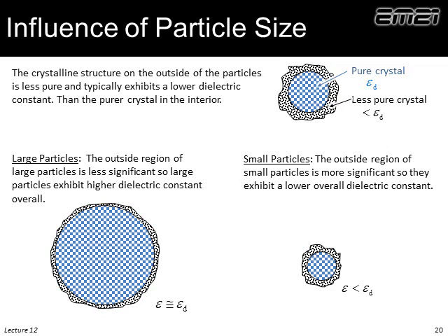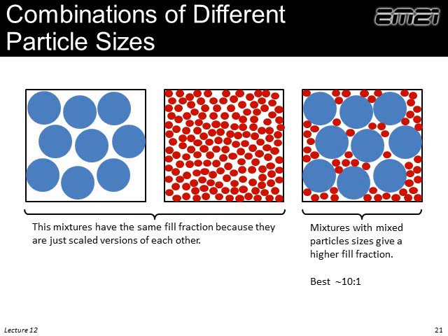However, on the manufacturing side, the larger particles limit how small of features we can realize, mechanisms of how we dispense them or manufacture with them. So from a manufacturing process perspective, we want very small particles. But here's one problem that small particles can give us. Intuitively, we know if we're loading a host with some kind of powder, the more powder we can get in there per unit volume, the more that powder can dominate the electromagnetic properties.